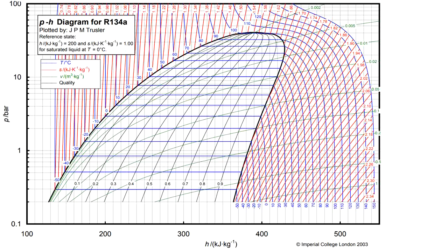And then as we are going into the superheated vapor, the isotherm goes down almost into a vertical line. So for example, if we would be at the saturated vapor point and we would increase the pressure, it would be a horizontal line going to higher and higher temperature.